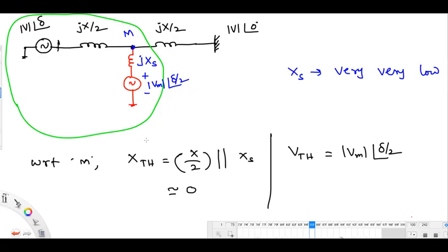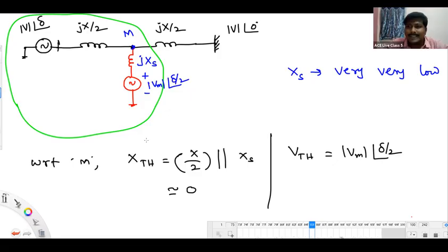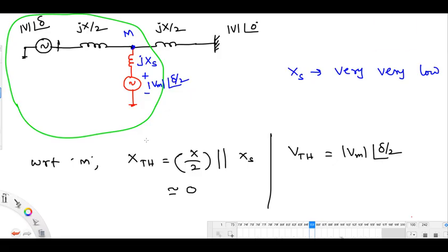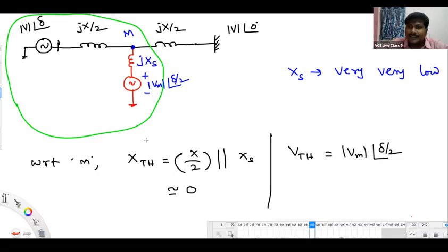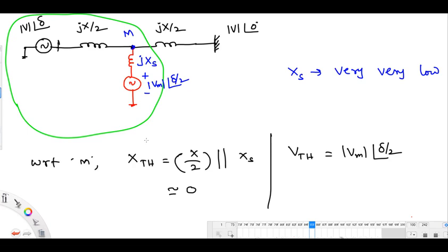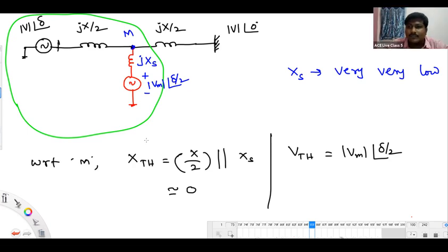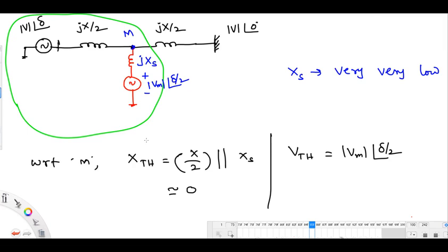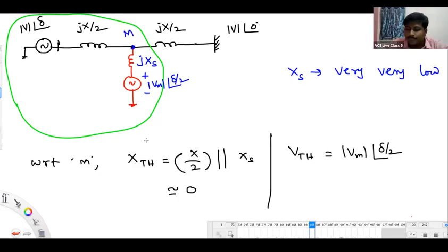The synchronizing power coefficient is Pmax cos delta, sir. Okay, that is, dp by d delta is the synchronizing power coefficient. Yes, sir. Okay, what is the steady state stability limit? Pmax into sin delta. Pmax, that's it, Pmax. Sorry, sir. Steady state stability limit is P maximum.